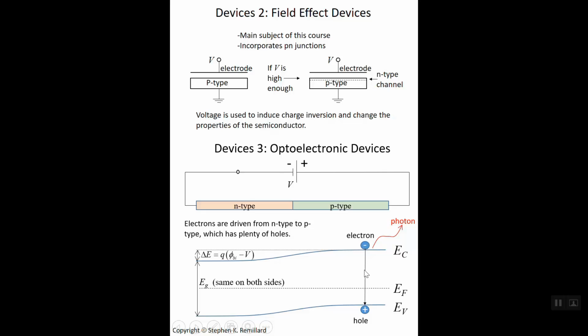When they're over there, they find a hole, and what is a hole except an electron vacancy? So an electron sees a vacancy down there in the valence band where the energy is much lower, so that's preferable, so it goes there. And in the process of going down to the vacancy, it emits a photon. Electron hole annihilation produces a photon, and you might say, what's the chances of that? Because the holes will also diffuse over into the n-type side, and you might not have sufficient electrons and holes in the same region to get a lot of light, and that would actually be very true.